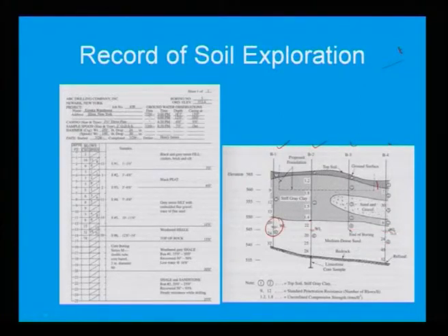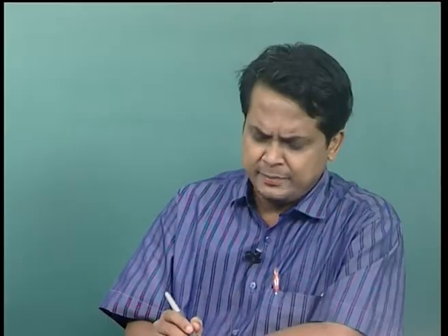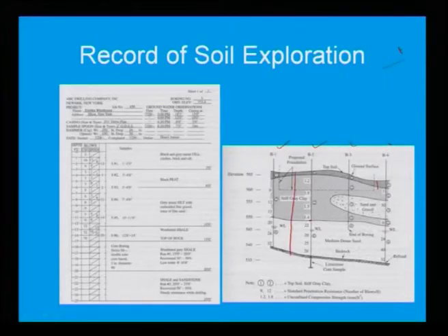So, now the third part is, where is your bedrock, whether this foundation is a shallow foundation or deep foundation. Depending upon the soil profile you have to decide where you want to provide your foundation, at a shallow depth or deeper depth. If you consider these two layers, I do not think a shallow foundation is possible, because this is a fine grained soil, silty grey clay. Then in that case what will happen? You look for other alternative arrangement. What other alternative arrangement? Other alternative arrangement is a deep foundation in the form of pile.